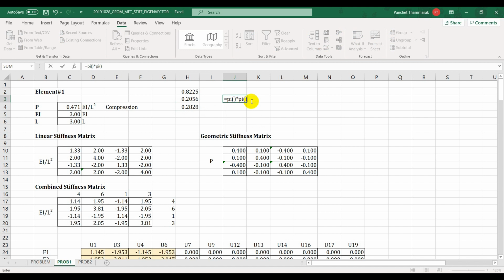If you look at the left hand side column, let's check the pi square times EI, which is equal to 1, divided by L, which is 4 square. So that's a 16. That's the upper bound value that is possible for the right hand side, whereas the lower bound will be associated with the cantilever column case, right?